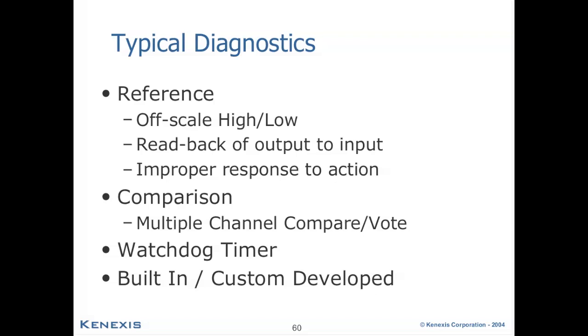Logic solvers may compare the results of a system with multiple components and move the process to a safe state if there should be, for instance, a disagreement in voting or communication. For software, a watchdog timer can be used to detect a certain amount of time of inactivity from the system, at which point the software will take an action to safely shut down the system. And certain instrumentation will also contain built-in and custom-developed diagnostics, which may be provided by the vendor or the manufacturer.